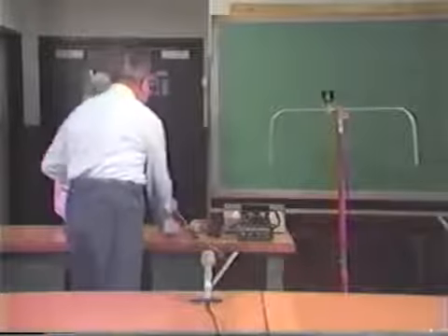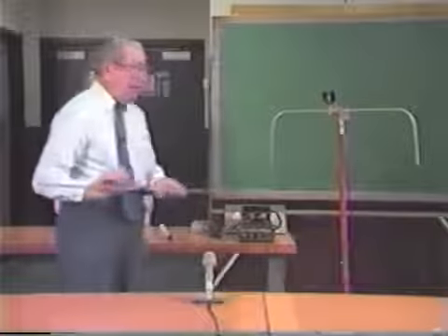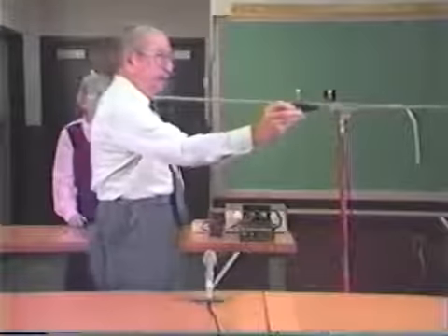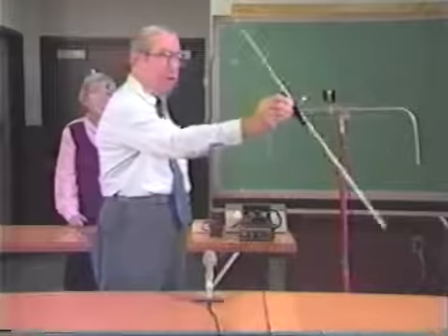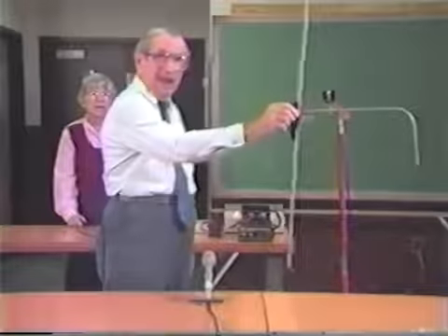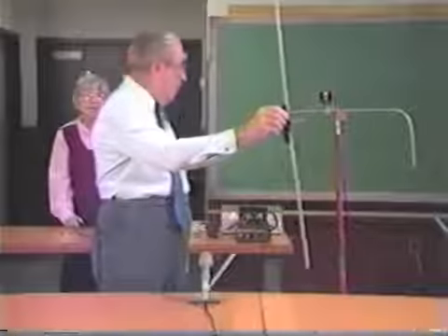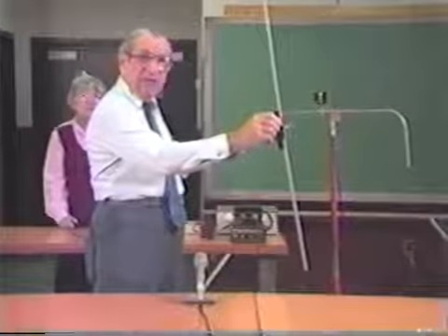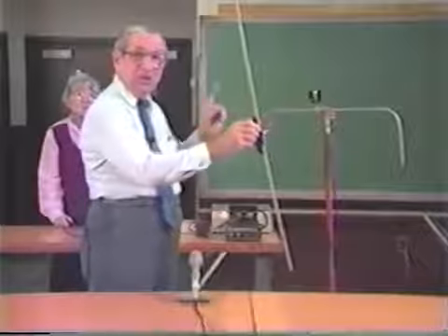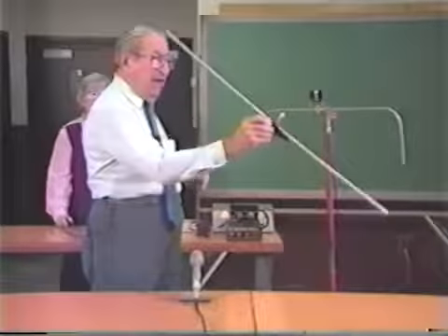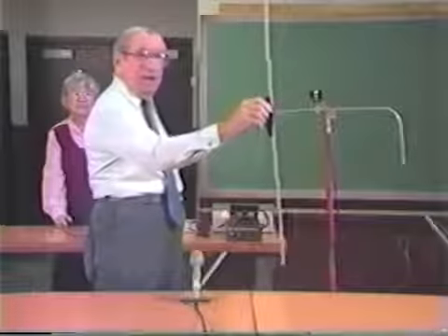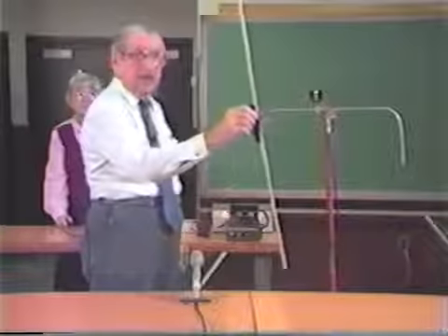Now, with this bent dipole, I want you to take a look at the polarization. Horizontally polarized. This should give you a very definite understanding that even though these ends are part of the antenna itself, and it's one bar of aluminum, the current portion is the portion that's doing the radiating, and therefore when I have this in its plane, it radiates. In the horizontal plane, the voltage portion does not radiate.